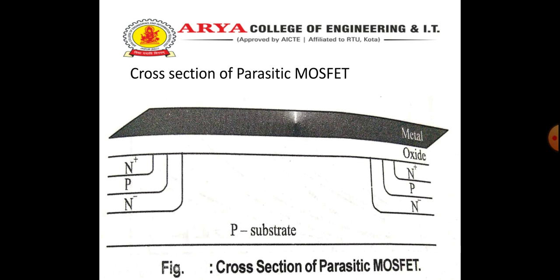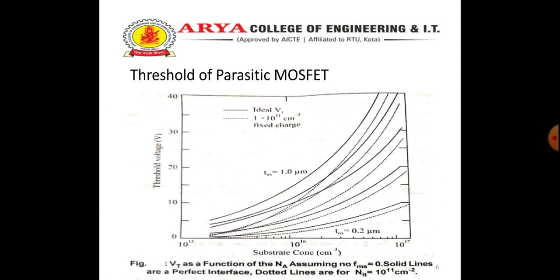If we apply a large positive voltage to the metal line, the surface of the area underlying may invert, turning on the parasitic MOSFET. The threshold of the parasitic MOSFET should be at least twice the supply voltage, which ensures that they will not turn on even in the presence of excess supply voltage or voltage spikes on the supply line, nor will leakage current be excessive. The plot of threshold voltage as a function of substrate concentration is shown in this figure. To achieve a suitably large parasitic threshold, we should select a thick field oxide or large substrate concentration.